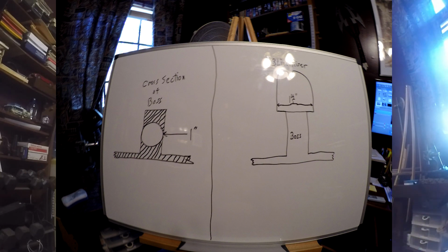So remember, you have to have risers where there isn't a casting that's all totally uniform thickness. And even if you're making a casting that has uniform thickness, it's a good idea to put a riser on the outside edge of that so that you won't have anything in the middle solidifying.